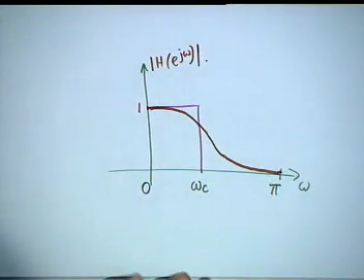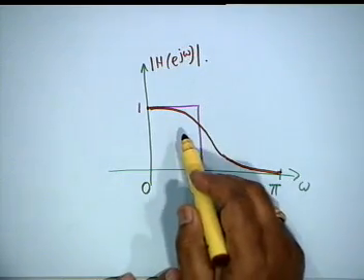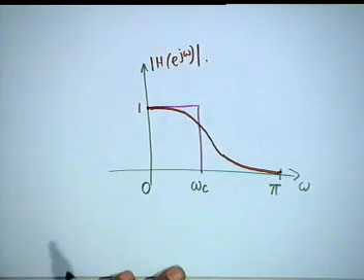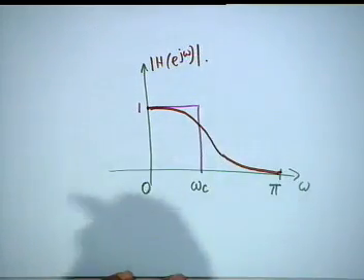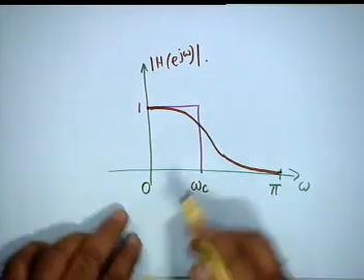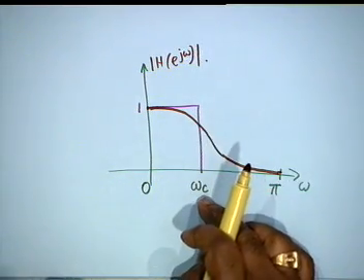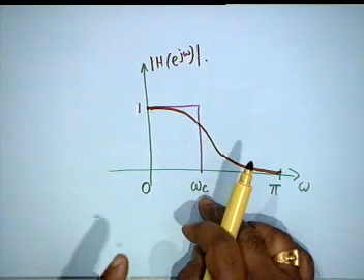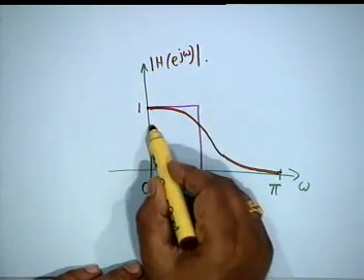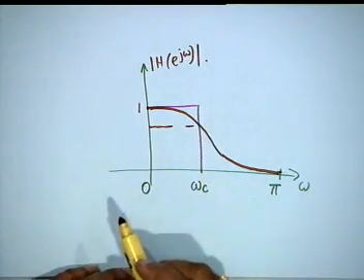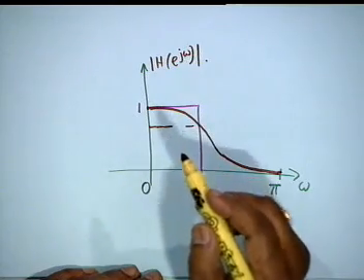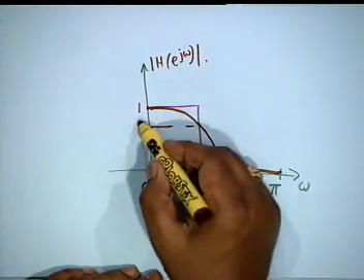We are not considering phase. The magnitude characteristic, simplest is that it is monotonic throughout. Now, we have to define, if it is an ideal characteristic, then omega sub c is the cutoff frequency. We define a cutoff frequency as the frequency within which the magnitude does not fall below, let us say, some quantity alpha.